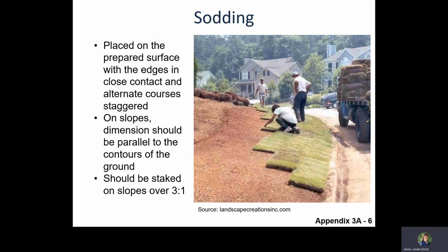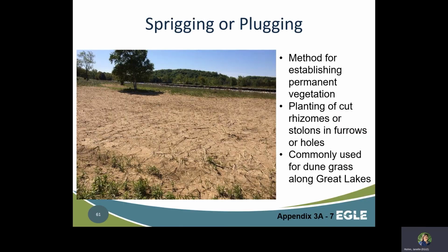It should be staggered or shingled to prevent water droplets from following an uninterrupted pathway straight down the slope, which can cause real erosion. Sod must be watered during the first season or establishment of the turf grass may fail. Sprigging may be done using a machine that cuts grooves into the soil, then mashes sprigs of grass into the grooves.